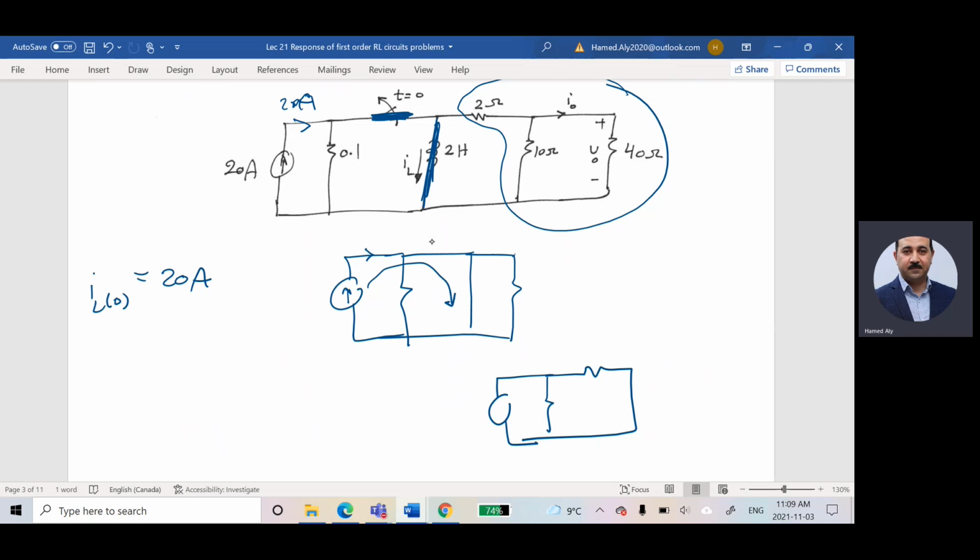Are you seeing what I'm talking about? This is not the scenario for that problem, but I'm imagining if I have a resistor connected here. At that time, this resistor is this. At that time, this guy is short circuit. The current here will be distributed between this guy and this guy based on the current divider identity. I have to pay your attention to that. This is one of the tricks I'm using in the final exam. Okay? Any question?